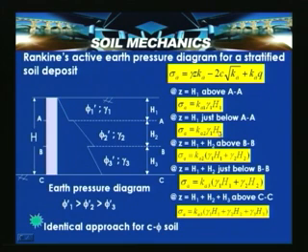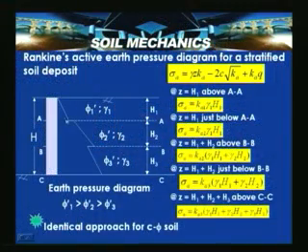One simple methodology one should understand here is that for computing earth pressures, you consider the top soil as a surcharge. Suppose my retaining wall starts from here; at this level AA, how will you calculate? Suppose gamma 1 H1 is the surcharge acting on this particular level, then we calculate that sigma A is equal to Ka2 gamma 1 H1. So just consider the topsoil as a surcharge, and then transfer that to a lateral pressure.